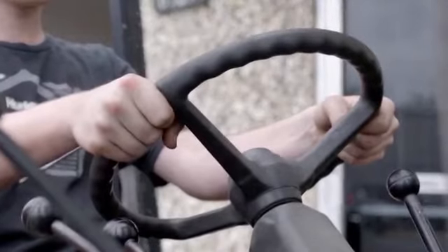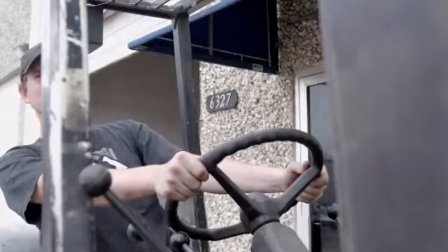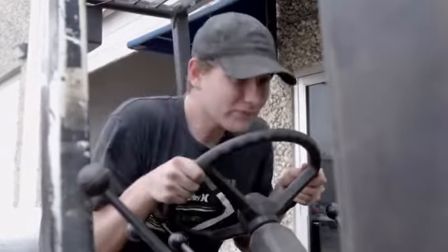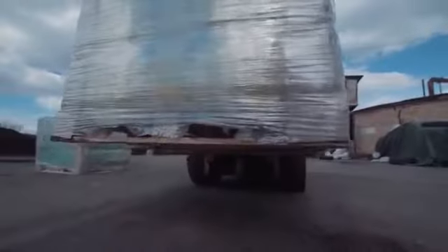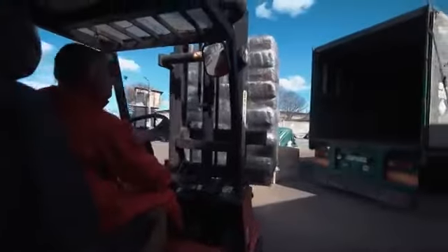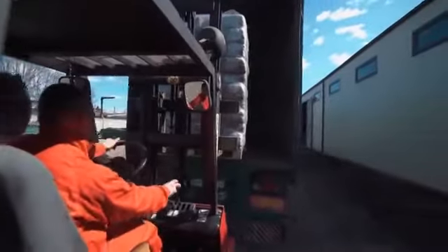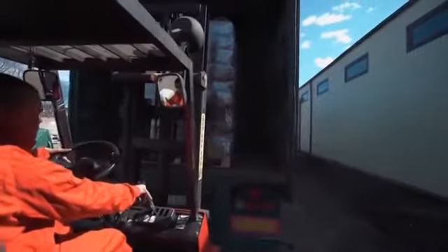Hold tight to the steering wheel. Brace your feet. Lean away from the impact. Lean forward. Tip-over procedures vary depending upon the type of forklift. It is important that you understand the type of forklift you are using and know how to protect yourself in the event you are involved in a tip-over.